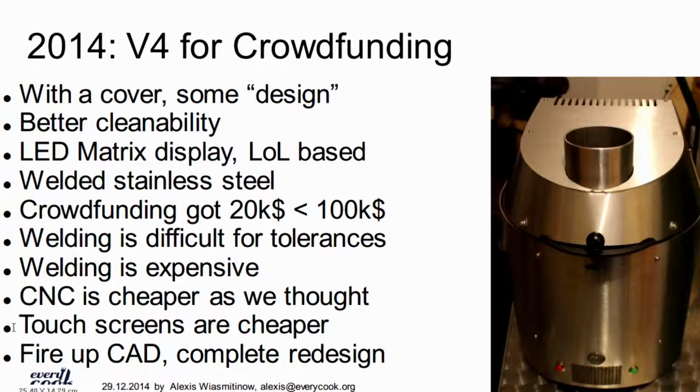We made the whole device in welded stainless steel sheet metal, which in the end was not the best idea, because through the welding we got lots of issues with tolerances.